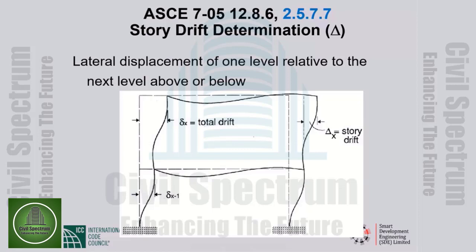If the non-structural components and the equipment supported on the roofs are not damaged, then there is a reasonable expectation that the facility will go on functioning during and following an earthquake. There is a control of property damage aspect also to drift check. So this is beyond life safety. I do want to emphasize that. Now, interstory drift is the deflection at the top of a story minus the deflection at the bottom of the same story. That is the first thing.